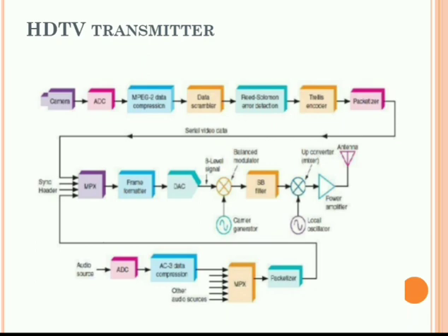The signal is next sent to the data randomizer. The randomizer scrambles or randomizes the signal. Scrambling or randomizing is done in that block. This is done to ensure that random data is transmitted even when no video is present, or when the video is a constant value for many scan lines. This permits clock recovery at the receiver.